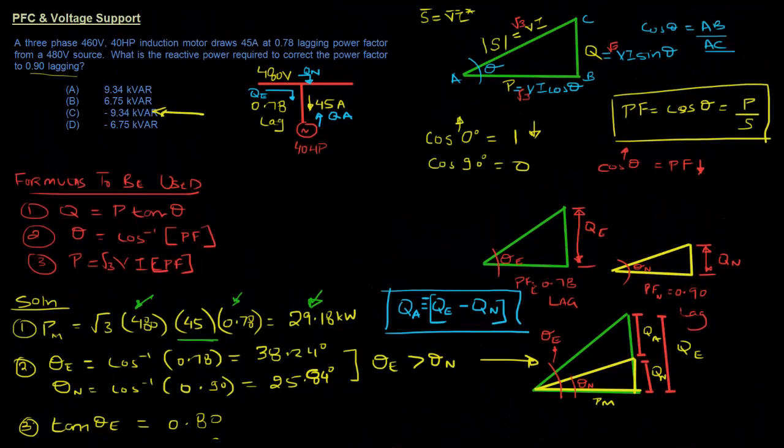A better power factor leads to smaller currents, and smaller currents has a lot of advantages. You can size your equipment to be a lot smaller. Your conductor sizes are going to be smaller. Your I square R losses are going to be a lot smaller. Your equipment life is going to increase. Your kVA rating is going to be a lot smaller.